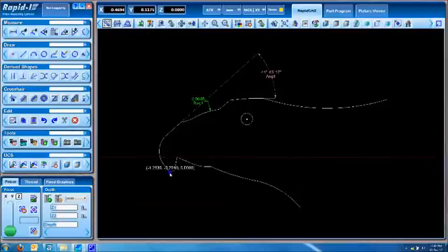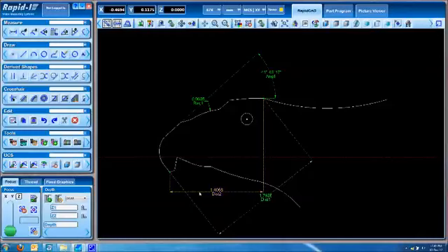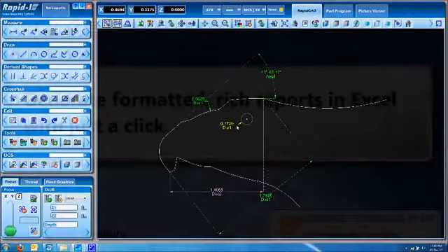If you want the point-to-point distance, click on the point, and you get the geometric distance. If you want the X and Y shift for your CNC programming, choose the same 2 points in the linear mode, move your mouse to the left or right, you get the Y shift, and move it up or down to get the X shift. Once you're happy, click to fix it. If you want the diameter, double click on the circle and you get the diameter.